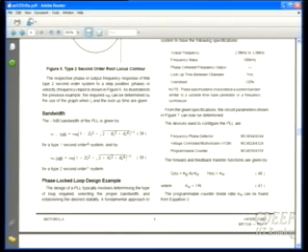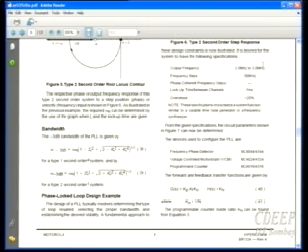And then bandwidth. Okay. Now this is a design example. Consider we want to generate frequencies from 2 megahertz to 3 megahertz. Okay. And then with frequency steps of 100 kilohertz. We want to have phase coherent frequency output. Do you know what is phase coherent?